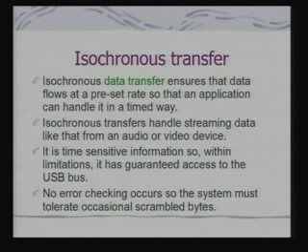The last one is isochronous transfer. What is isochronous data transfer? Isochronous data transfer ensures that data flows at a preset rate, this is fixed rate, so that an application can handle it in a timed way. So, isochronous transfer is primarily targeted for time critical delivery of data.